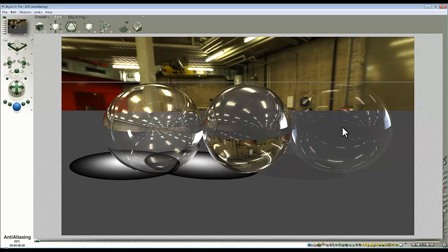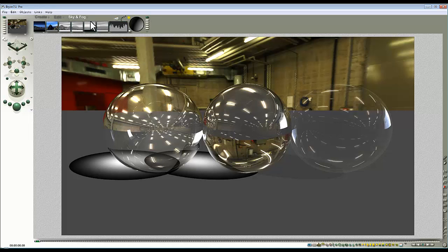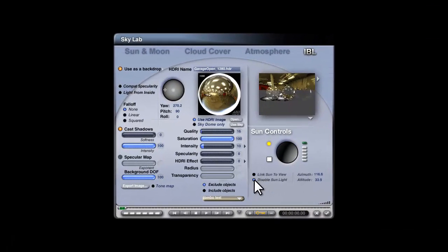We've got this attenuation in the middle, so that does sort of work, though I'm not sure about the shadow situation. I suppose that seems appropriate. Perhaps the answer here is to upgrade the type of lighting we're using. So I'll disable the sunlight and then bring in high dynamic range lighting, and then try and set it at an appropriate level so it doesn't look overly bright.